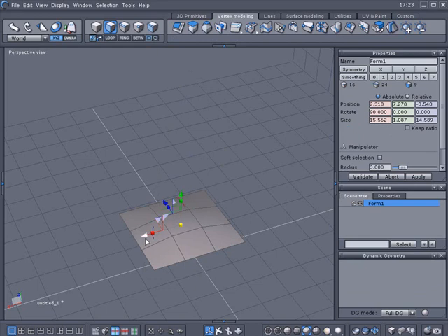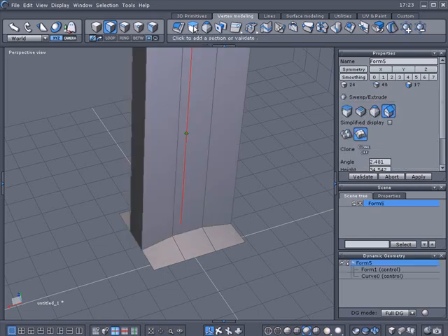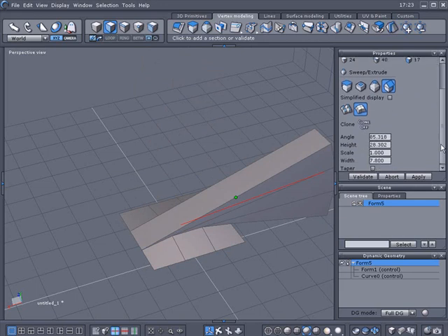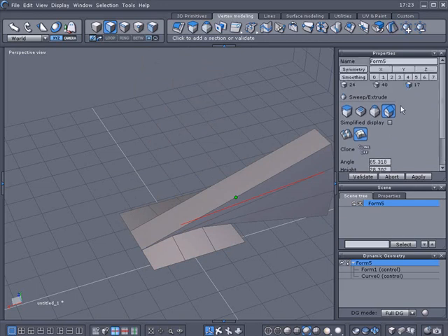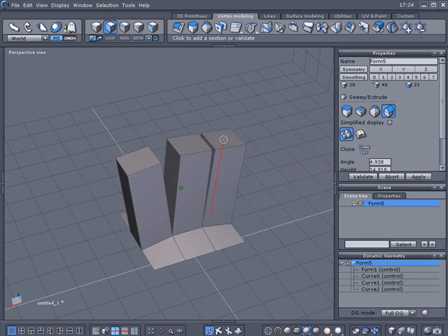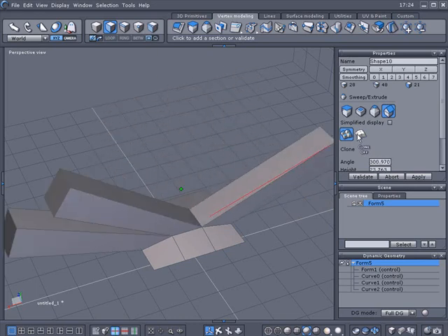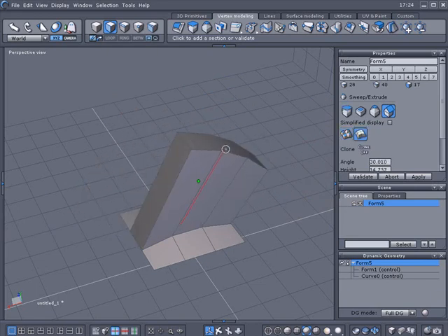At this time, I'm going to select one of the faces and drag over it and select three of them. I'm going to select the sweep surface, and as you can see, it's extruded all three of these faces in groups. And you need to pull this down here for a lot of extra options. Now, if I select this option over here, this keeps them as separate faces. So this is how this happens. As you can see here, if I want to keep them grouped together as a block, I can do it like that.